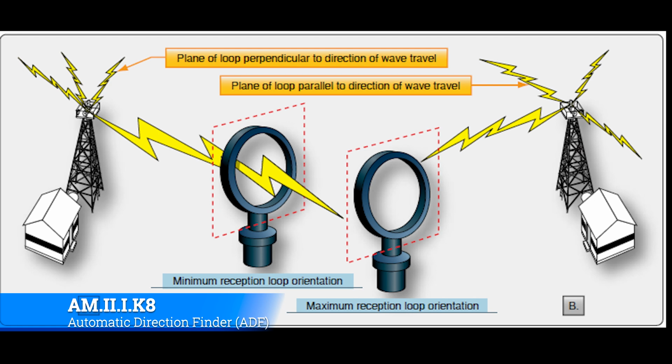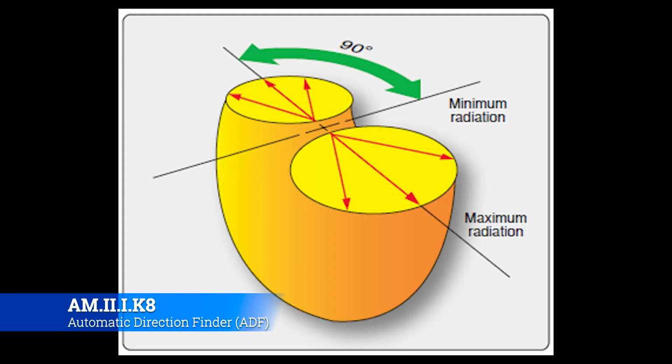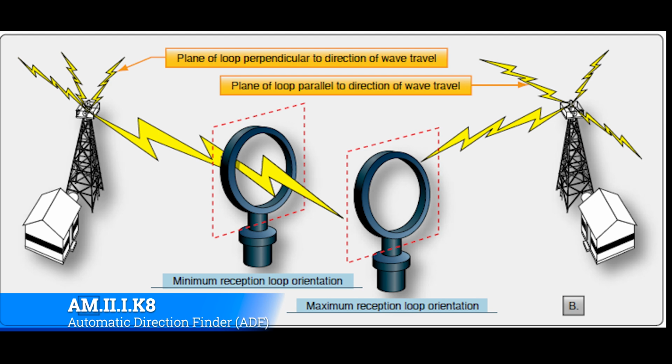Okay, so let's talk about these loop antennas. These antennas are actually kind of iconic for those 1920s, 1930s, and into the 40s, and even up to the 50s aircraft, depending on where you look. They are highly sensitive to direction because of the way that they are lobed, and I'll put that donut graphic up. Imagine looking at this antenna. Imagine a donut of sensitivity outlined around that loop. As signals hit it from the front, it says, hey, this is the direction it's coming from, and then you could turn the plane towards it.